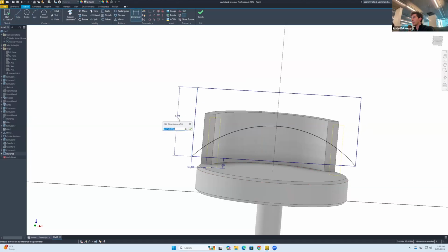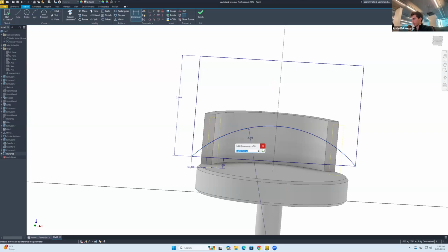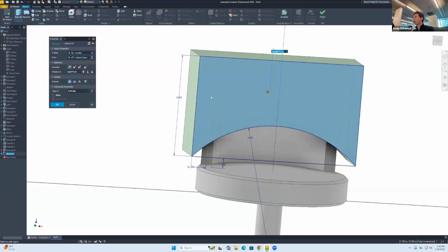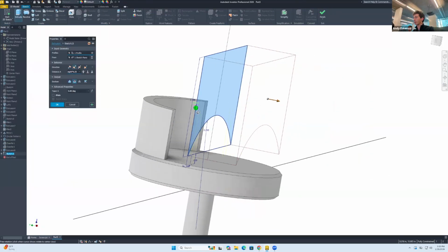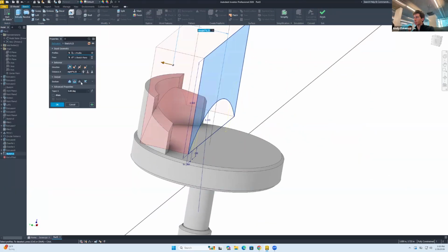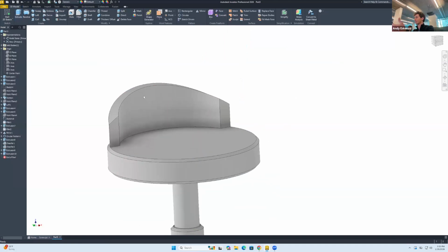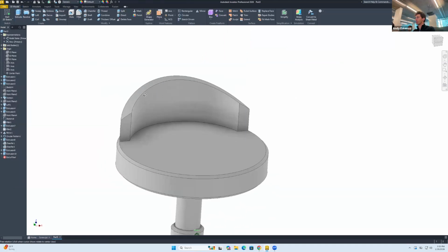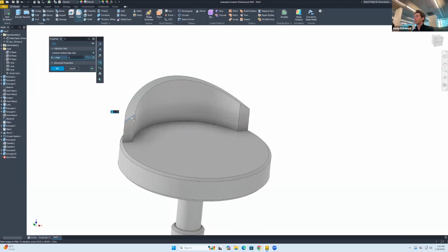This is that idea of shaving stuff out. What do I mean? This might give us an error, but extrude, cut. But we're gonna go on that direction and all the way through. So now you have a smoother looking side, and let's beautify it with a big fillet in there, 0.5.